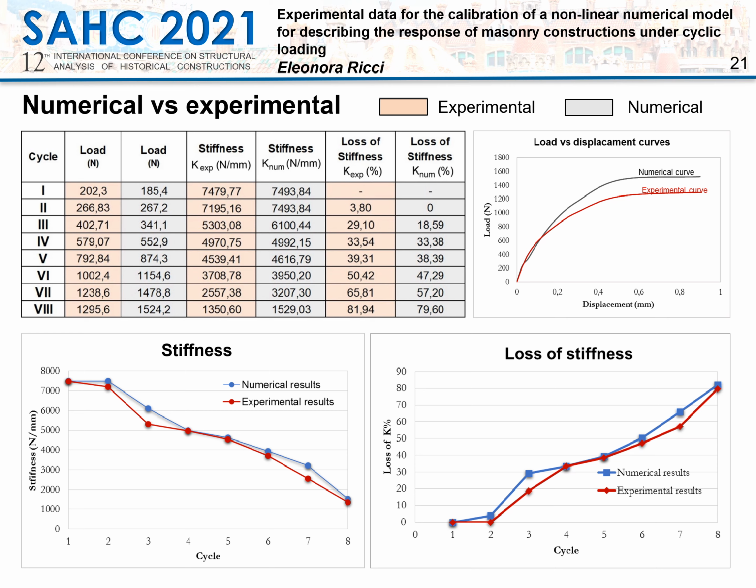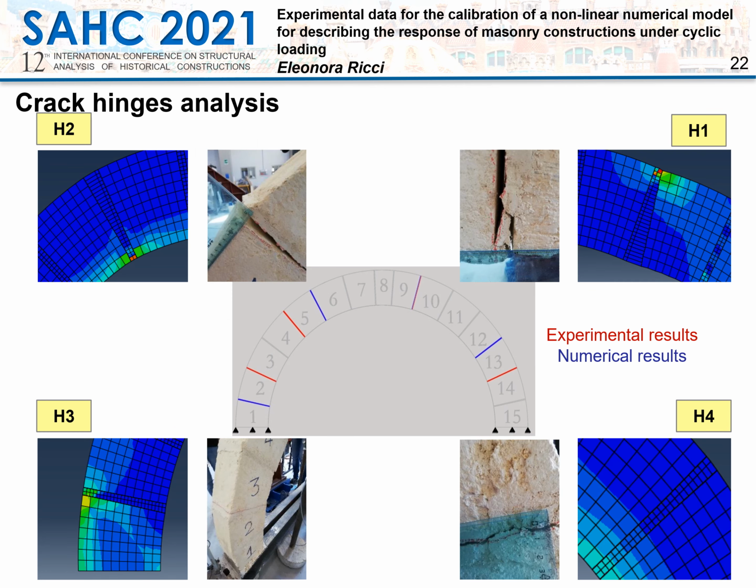Considering that we employed a continuous finite element model developed by a commercial code, avoiding the complexity of using interfaces or distinct element model approach, the results are very interesting. Finally, for what concerns the location of hinges, in 3 cases the numerical model locates the hinge at the next joint with respect to the position of the experimentally observed hinge. This minor difference can be due to the slight slidings at the supports observed in the experimental test, which were prevented in the numerical model by the considered boundary conditions.